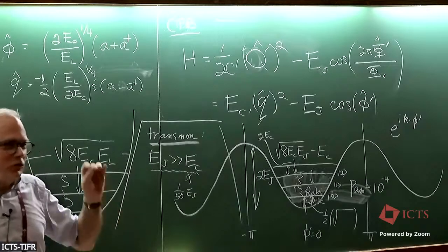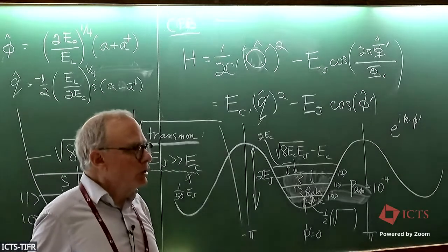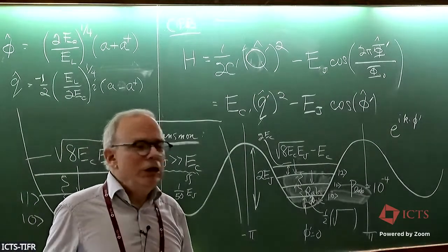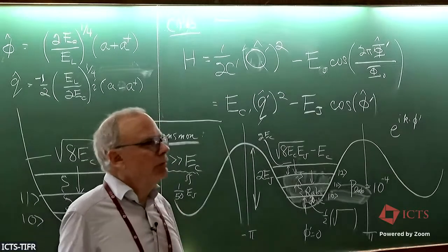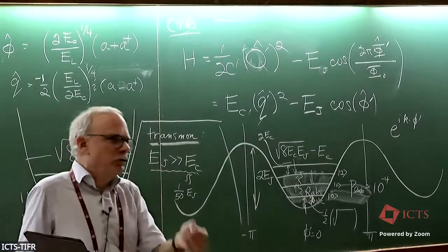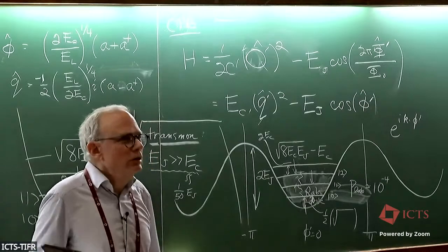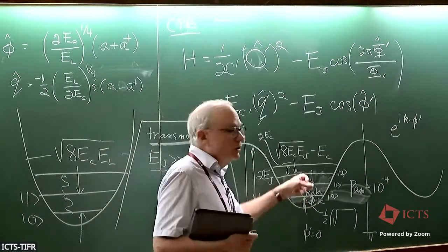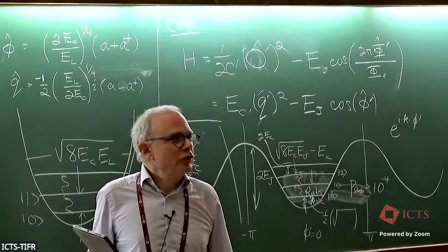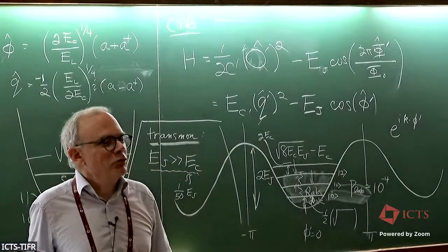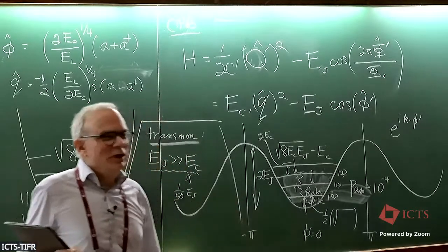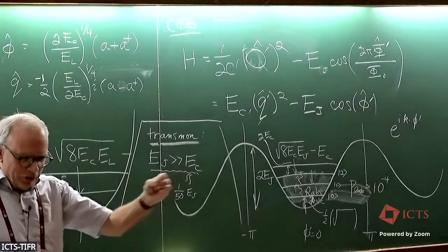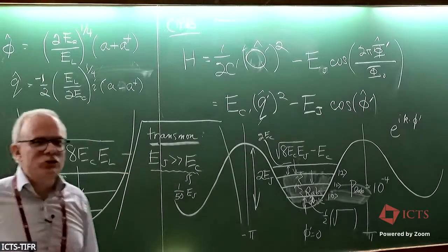But this knowledge is not automatic. If some very eager student says, oh, I know how to do Rabi driving and it will be 10 times faster, and they just crank up the signal, sure enough, they've got the 0-1 going 10 times faster. However, the leakage rate's gone up to 5%. Whoops, okay. So there are really dangerous directions in parameter space in these circuits.